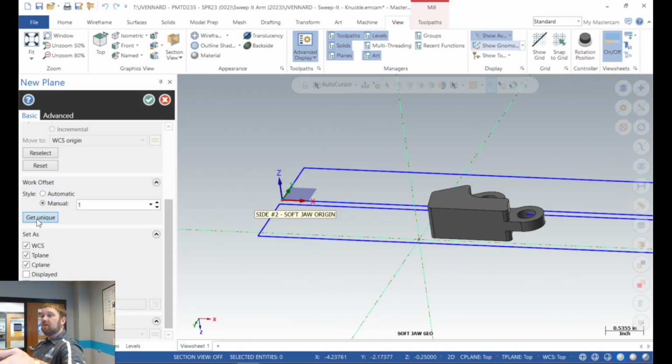So if we were making these parts and I had to make bunches and bunches of these, one thing I would do first off is I'd utilize my vise more. So I'd probably be making 3 side 1s in one vise, with a little stop for each one of them. And then in the second vise, I'd have 3 of the pockets we're getting ready to cut, so I can take them from vise 1 to vise 2, and then if I had a bigger machine, I'd have a vise 3 to do the third side ops, which is to bore that bore in the end of the part.